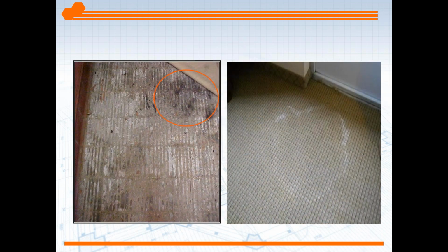As I already mentioned, any and all floor coverings will suffer from excess moisture vapor in the concrete. Even something as simple as carpet can have staining on the surface and the potential for mold growth. So again, moisture mitigation is important even under this type of installation.